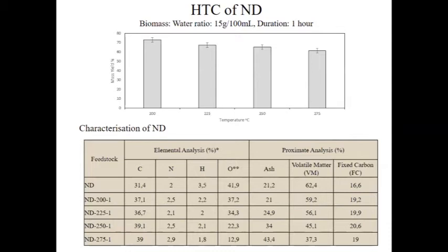Same with the others, for Narlısaray dry digestate, mass yield also decreases with increasing temperature. Comparing the Narlısaray biomass and the hydrocharred digestate, the digestate has higher ash content. This unwanted increase in ash content is caused by the inoculum used during the fermentation, which has a high amount of inorganics.